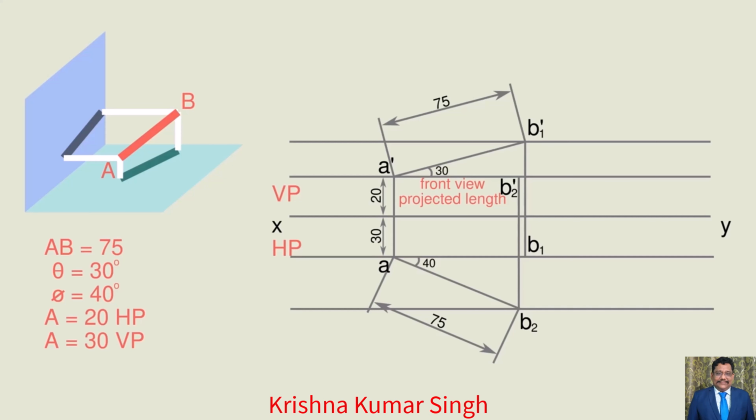Step 3. Now we are merging step 1 and step 2. Now take the compass by fixing a length of AB1 and draw the locus arc from point B1 until it touches the locus line and name it as point B. Join point A and point B. This is nothing but the original and final top view projection made on HP.